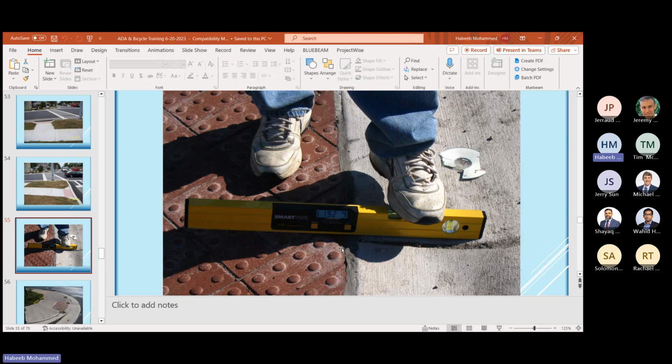I mean, nowadays you can get it, you have to go to Home Depot or something, but that's one thing. And also, is it in percentage or is it in degrees? You need to be careful about that. Sometimes you might accidentally hit the button and it's measuring in degrees, but you make the note that it's percentage, which is not right. So make sure about that when you are doing these measurements.